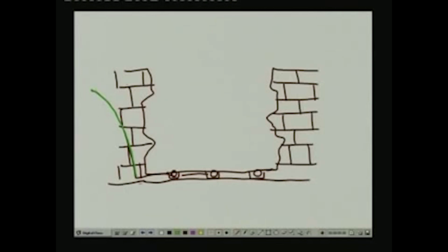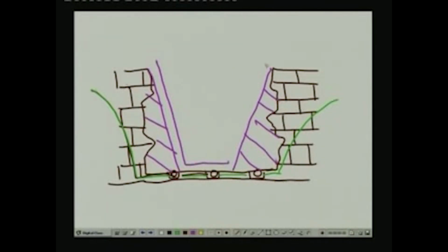So let's say the groundwater table in this particular case is going to be drawn down like this, and then inside the excavation was a backfill placed like this, and inside the backfill was constructed a clay liner, and on top of the clay liner there was a geosynthetic membrane, geomembrane actually, impermeable geomembrane, and then waste was placed,